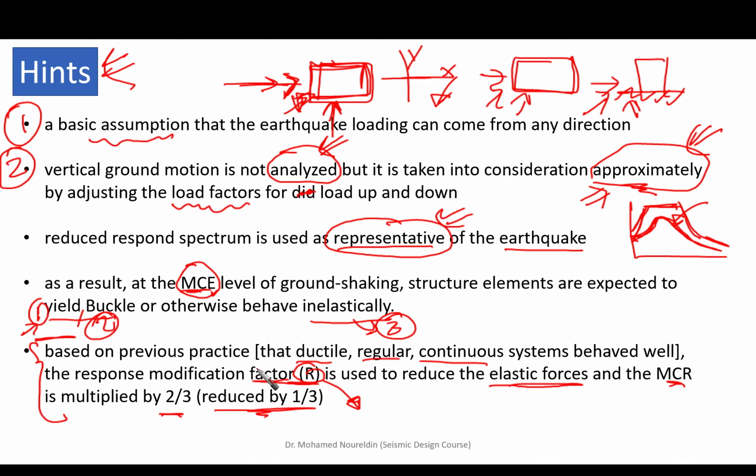Because of our experience from the previous systems, how did they behave? Well, we found by experience that whenever we design our structures to be ductile and regular and maintaining a continuous load path, they behaved very well during the previous earthquakes. Based on this, we tried to reduce the seismic demand by the concept of response modification factor to take into consideration the hysteretic